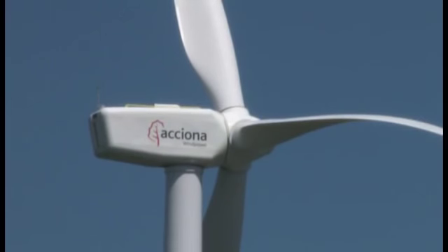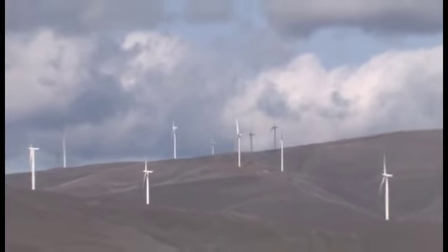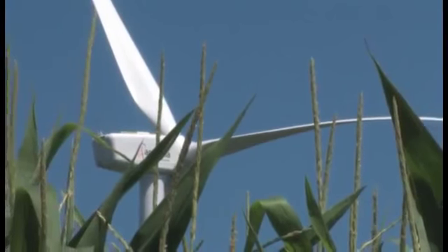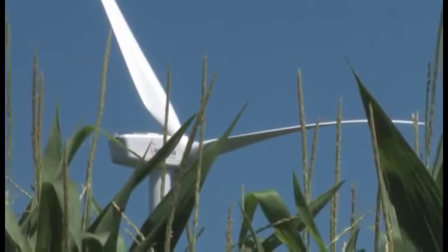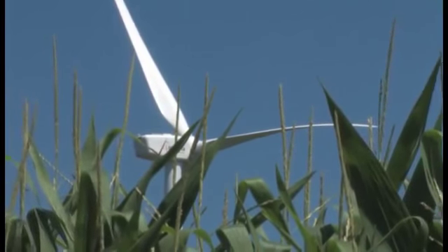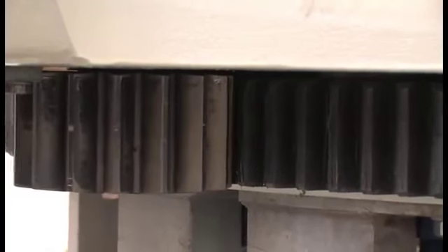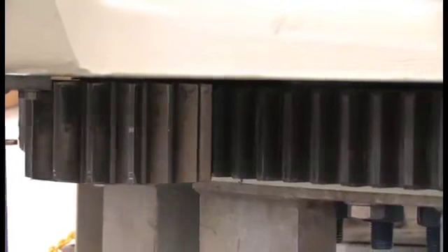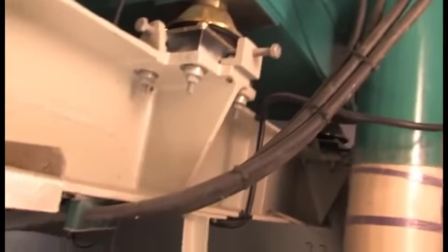During normal operation, when the wind speed is above 3 to 4 meters per second, the controller will keep the nacelle pointed into the wind and make corrections as the wind changes direction. During times of low or no wind, it is not necessary to keep the nacelle pointing into the wind. In fact, tracking a wind that is too low to produce power results in unnecessary wear on the yaw system. As the nacelle tracks the wind, the flexible power cables become twisted, but might untwist as the wind changes direction.